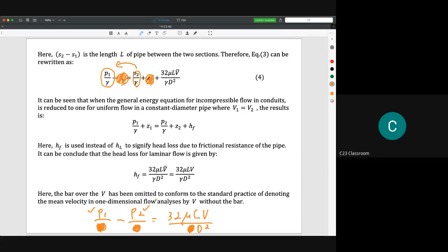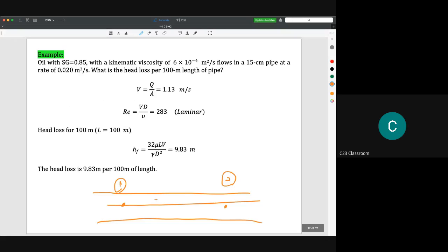So again, it will show us the pressure drop. That's why if you are talking about the flow in pipes, normally in real applications, they are talking about pressure drop. So why is pressure drop very important? Because to make sure that water can be supplied to its destination, to your house, it must achieve a certain level of pressure. So the pipe engineers will estimate, so after certain kilometers, they need to install another tank, another water tower or a pump house.